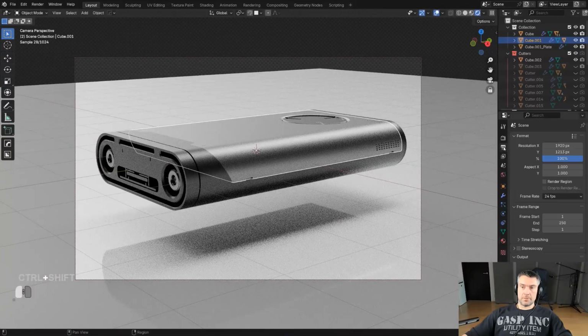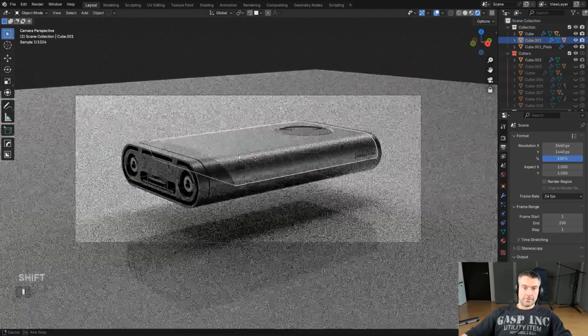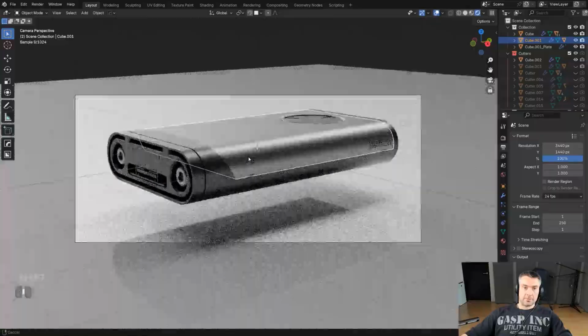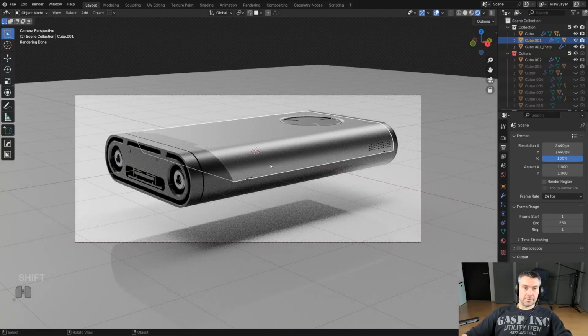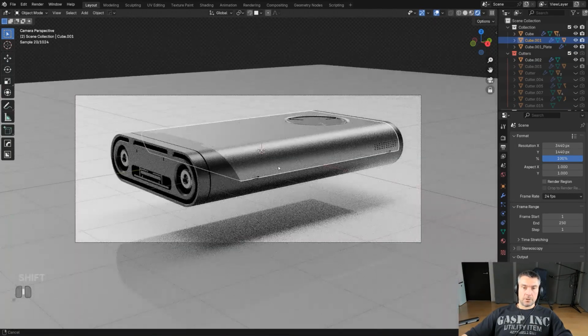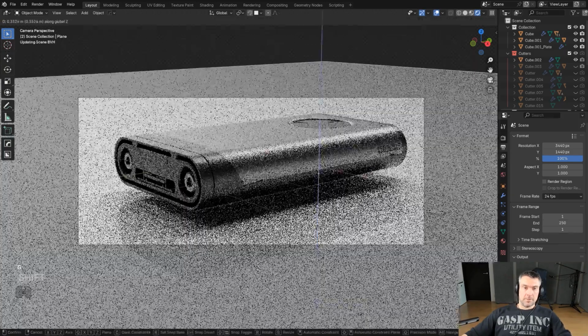We could actually change the ratio here to 3440 by 1440, which is going to be 21 by 9. I think it fits better because the object is kind of flat and sort of oblong. So we could do something like this. And you want to move it closer to this right hand side of the frame, because that's the front of the object. You want to leave it a bit more breathing space here, and also that's the main concentration of details. So you want to showcase that. It's really important. Okay, now let's unlock the camera from view, so when we move we don't disturb this. Now you have a choice with the floor.